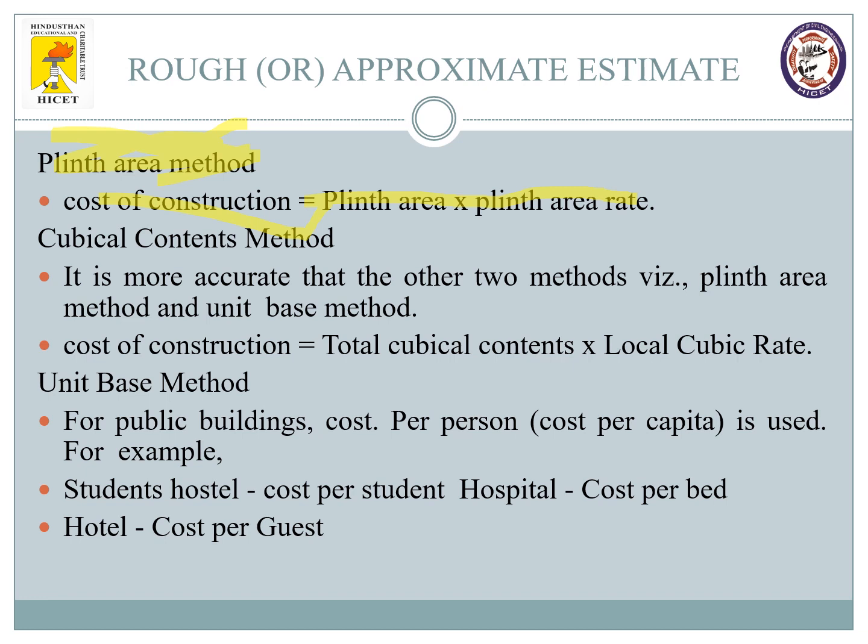We are going to calculate how many meter square of plinth area is there in the particular building, and we are going to multiply it by the plinth area rate. That is, we are going to fix one plinth area rate based on the location of the site. Each site will have different locations, and for different locations we'll have different rates for plinth. For example, if you are residing in Coimbatore, the plinth area rate might be around 1400 to 3500, it depends, based on the materials or quality of the materials to be used.